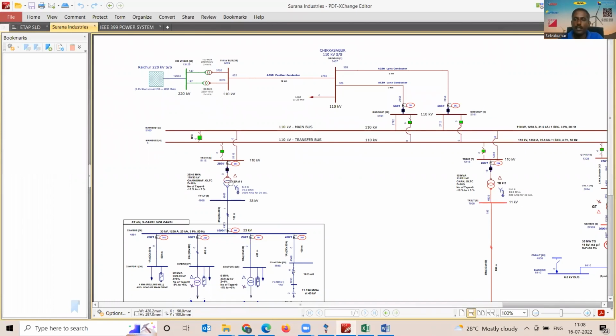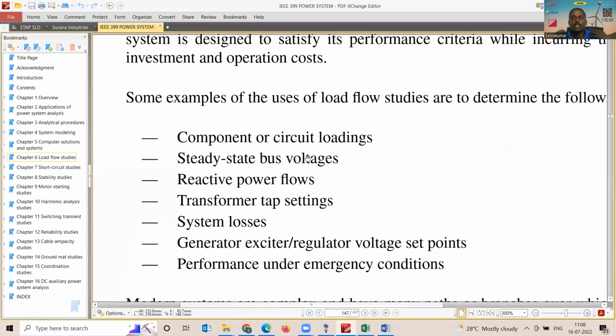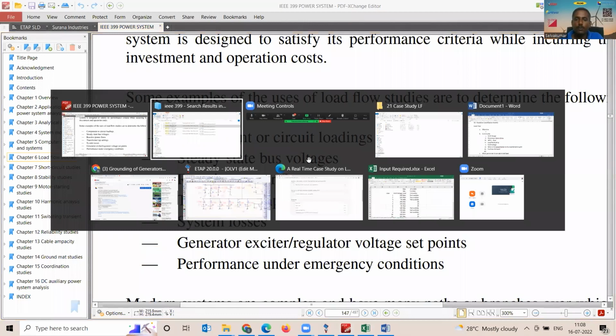It could include transformers, cables, transmission lines, etc. So that's the first objective, and you need to ensure what is the percentage loading of the transformer, what is the percentage loading of the cable, what is the available transfer capacity (ATC) in the transmission lines for future use. So that's another important aspect, I guess, which is in fact missed most of the time.